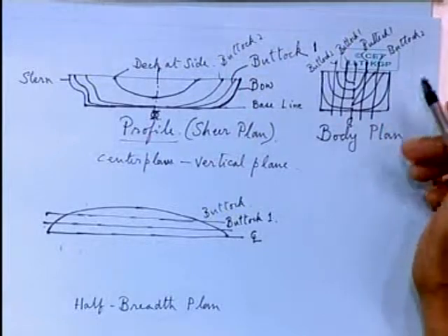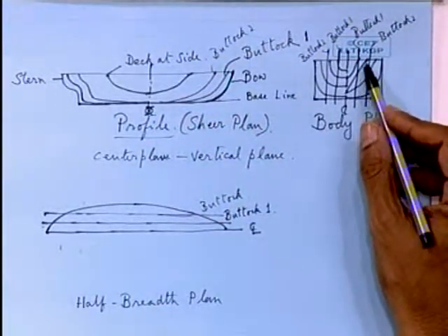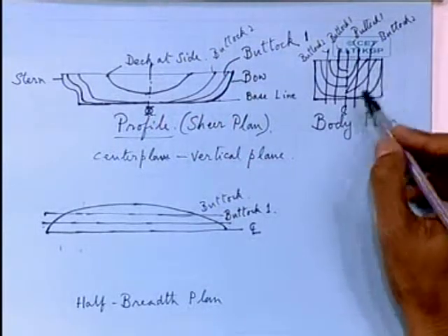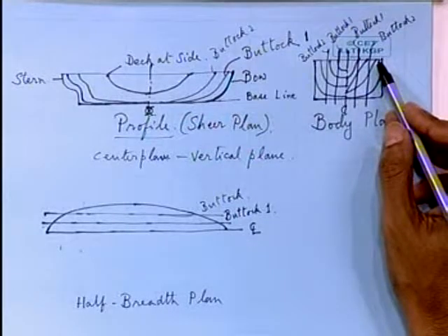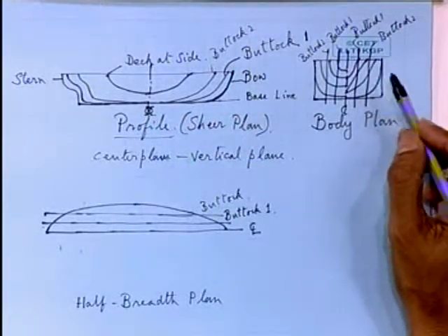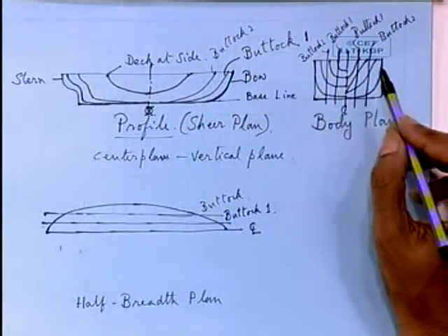Of course, wherever it is necessary, when you are fabricating the ship in the hull shop, you may be required to draw the full section. But then again, it should not be shown on the body plan. Otherwise, that will give an erroneous drawing.